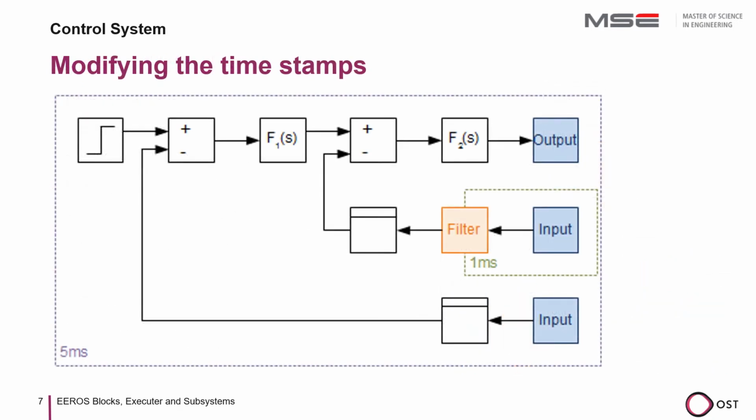Each signal carries a mandatory timestamp. A signal source, such as a trajectory planner, defines a value over time and therefore sets the timestamp corresponding to the generated signal. Blocks that read from an external source set their timestamp to the time the value was captured.